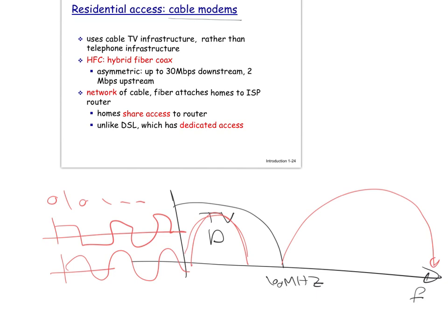We'll see now how the network architecture looks like. So instead of transferring this signal as is, we do some kind of modulation. We increase the frequency of the signal. So this signal, we shift it in the frequency domain. So TV broadcast will use baseband transmission, and the data transmission will be broadband. So we'll have to shift the signal in the frequency domain, so that we have no interference between the two.